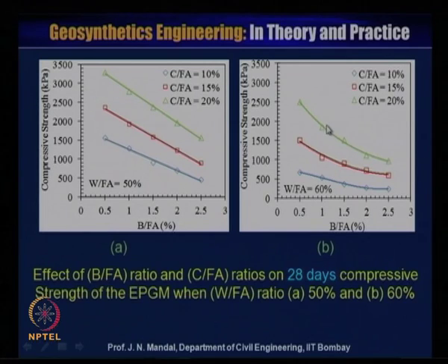But here also, when the water to fly ash ratio is 60%, it is not linear, and the compressive strength is lower than where the ratio is 50%.